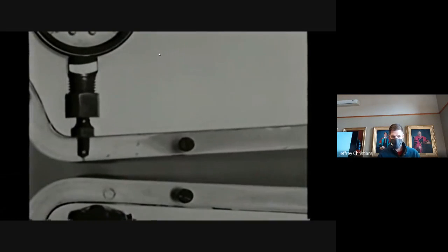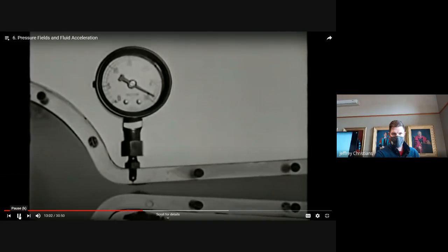When the absolute pressure is low enough, water changes to steam. You can't really read the gauge, but this line right there, you can see a little bit darker. That's 30 inches of mercury. That's like zero pressure. We get stuck at like 29 because that's the vapor pressure of water, 1 inch of mercury. So that last little bit, we get stuck there because that's where we actually start boiling the water. So you can see we get low enough pressures here that we're getting cavitation and seeing this boiling effect that we talked about last time.